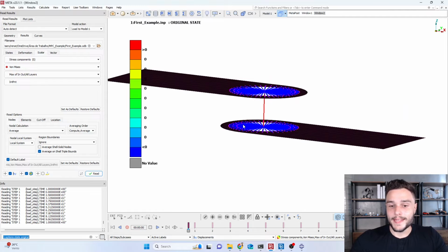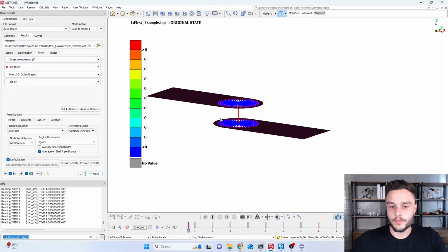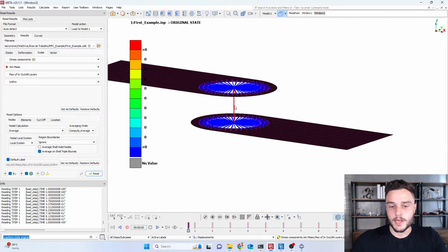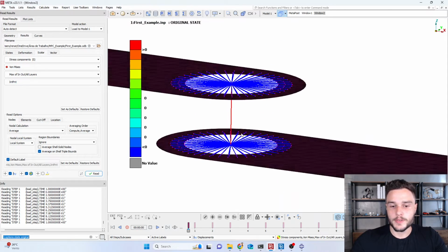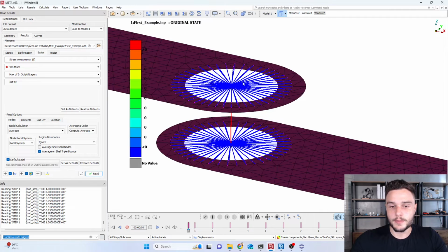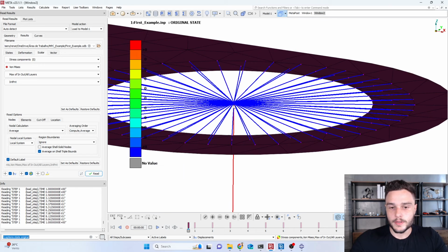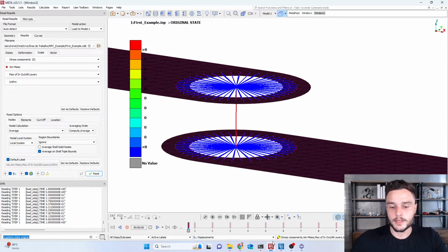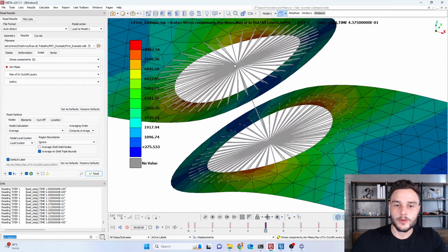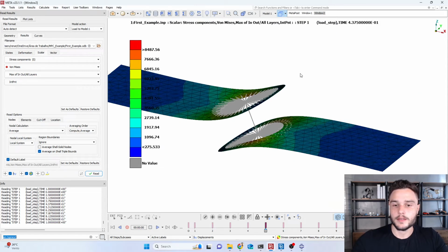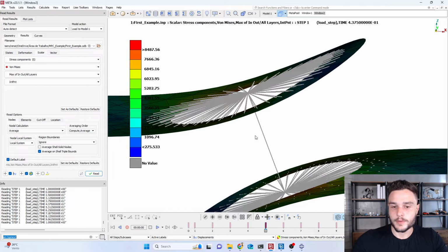Okay, so the idea of this example is to show in a visual way how this type of constraint works. You see that this is a rigid beam, that is, it doesn't deform, which means that the distance between these two nodes is kept constant. This upper node is rotated if the beam is rotated. So you see, look how this node right here is rotated in the counterclockwise direction, because we have the MPC rotating.